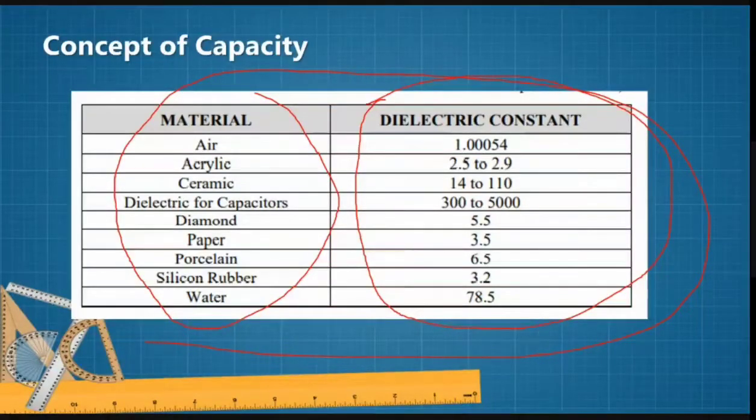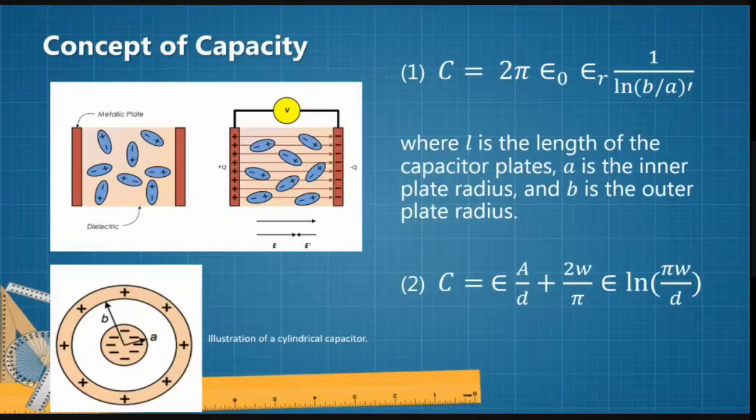Ideally, to make a capacitor, a dielectric constant that does not vary very much with frequency, as is the case of polyethylene, is desirable. And the capacitor can have many different forms. The most typical shape is the flat plate.